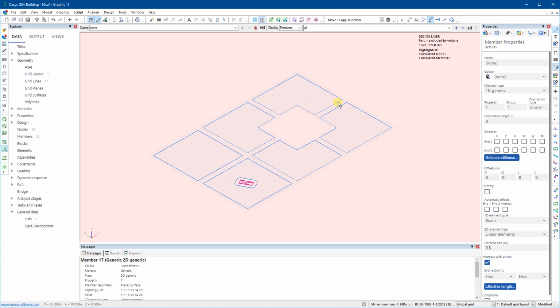So the point of that is that we can create our analysis model, put loads on it, but then maybe change the way we want to mesh it. We don't want to assign loads to particular element numbers because they might get deleted and recreated. If we assign loading based on groups, the elements created will always be associated with a group, so then the loading is always applied to them. That sounds a bit maybe convoluted, and I'll explain or show you a bit later when we look at applying the loads.